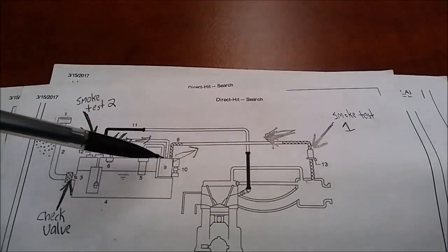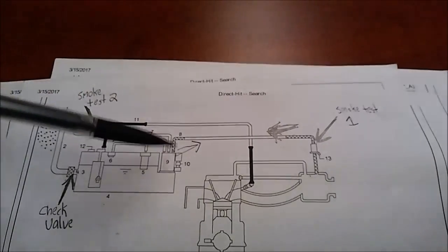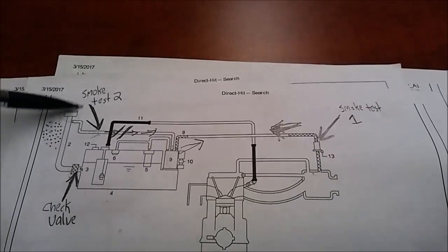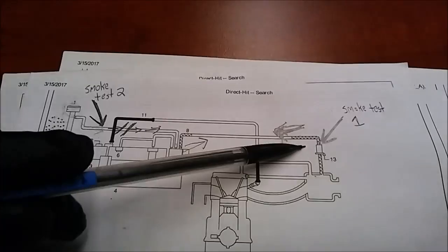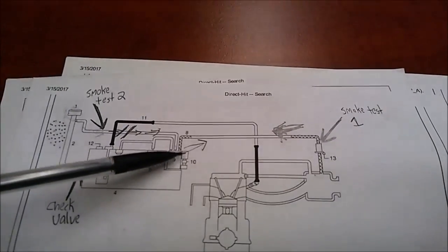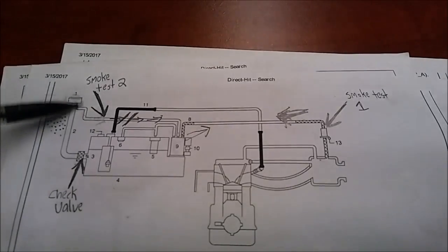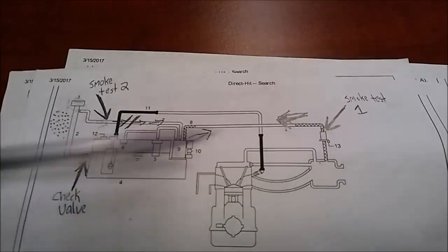I think that may have actually worked from that location. And the reason I said in the video that it didn't is because I wasn't seeing smoke out of this filler neck, where on most vehicles typically I will. So I think potentially we did have flow here, and I switched directions on that based off the fact that I couldn't get smoke out of the filler neck. So let's keep that in mind.